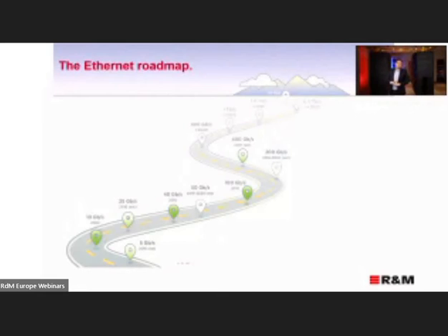If we look back and look into the future, we can observe increased bandwidth. Here on the screen, you can see the roadmap of different speeds. Also I will show you what kind of interfaces are required to run a certain application. So 5 gigabit today can be running easily with copper cabling with a standard RJ45 connector. Then a very popular application now, 10 gigabit, can run on both fiber optic and copper.